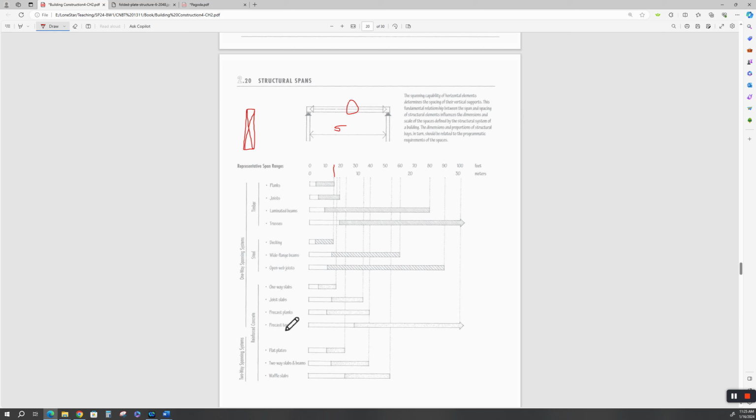Concrete. Concrete's rigid. We know that it likes to want to break apart, but it has some flexibility. One-way slabs can go up to, what is this, 20 feet? We'll say 20 feet, 15, whatever. Again, this is a rule of thumb. Your structural engineer will guide you in your planning phase for your job. But this is a good place to start. It's a rule of thumb.